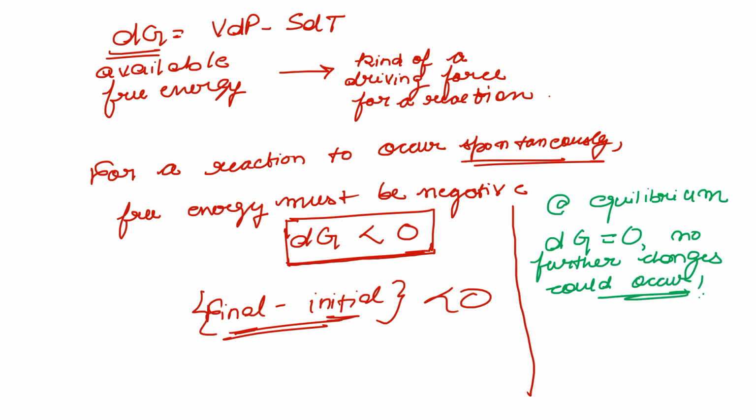And there's a reason why we take the free energy as a basis for the phase diagrams, and not different parameters. Like in thermodynamics, we have the Helmholtz free energy, we have the internal energy U, and so why do we take G and not these other energies as a criteria for our phase diagrams? Well, because it turns out the other thermodynamic parameters, like the Helmholtz free energy or the internal energy, are just another combinations of dependent variables.